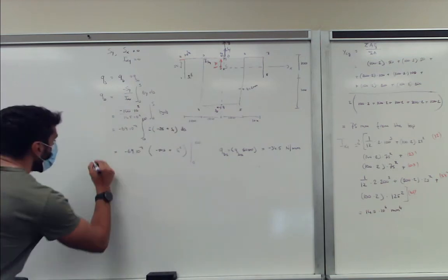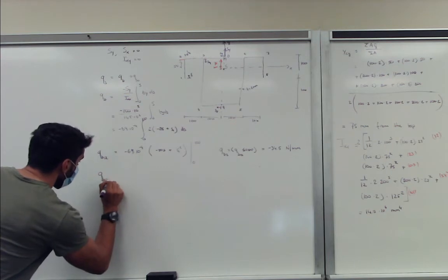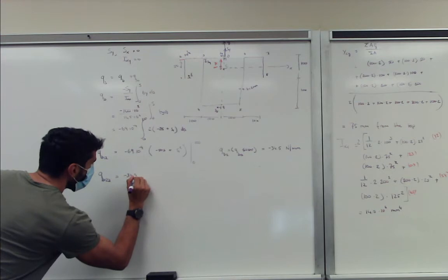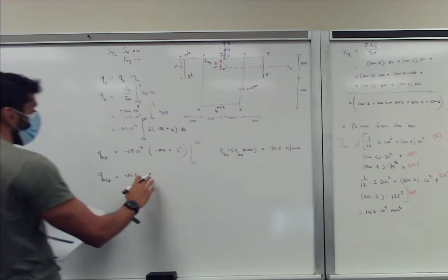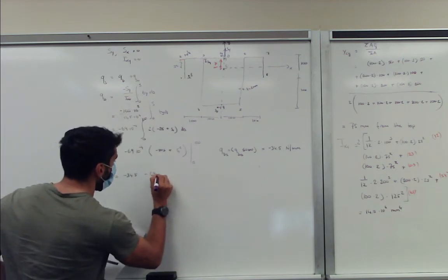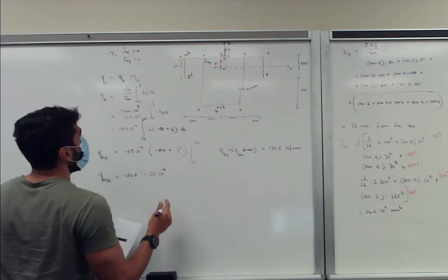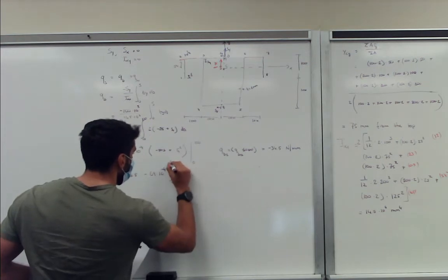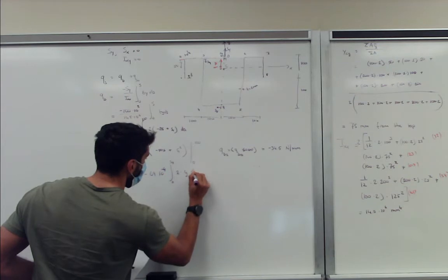So this is QB12, now we do QB23. We start at that value of minus 34.5, and we add this value, so it's negative, so it becomes minus 69 times 10 to the power minus 4 times the integral from 0 to S2 of t y ds.